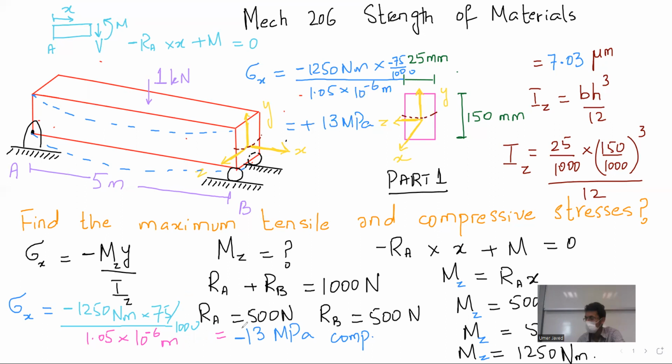Does it make sense? Oh yeah, for sure it does. Look, the load is acting like this. The beam is bending like this. The top surface will have compressive stress. So I'm getting the negative answer.